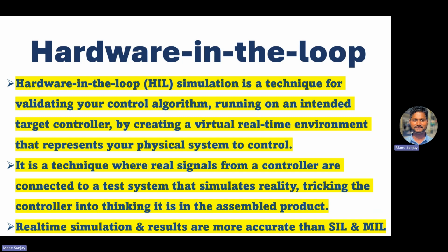Taking the example of the EMS, if you are feeding the crank and cam sensor inputs to the engine management system ECU, we have to simulate that using the real-time simulator and feed that input to the ECU. So we are fooling the ECU that it is actually connected to the real system. This is what is also written here: by creating the virtual real-time environment that represents your physical system to control.